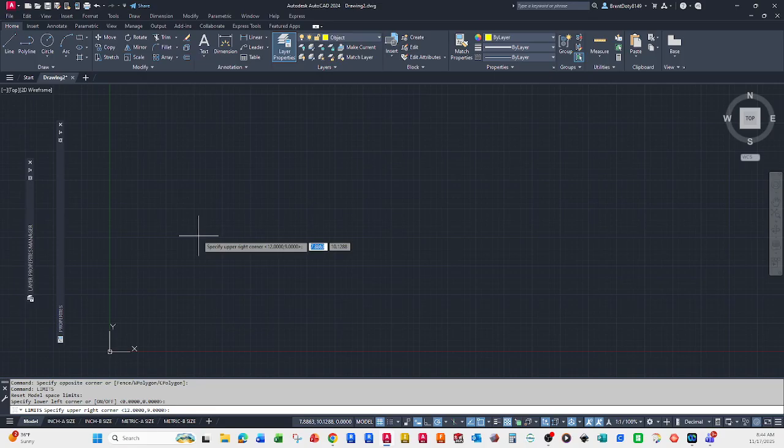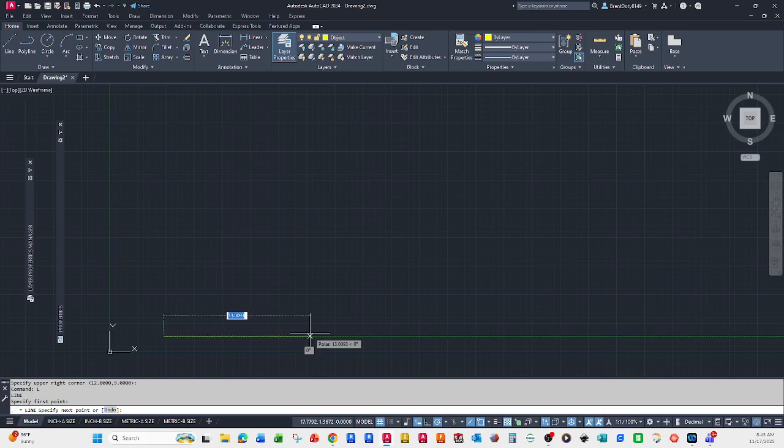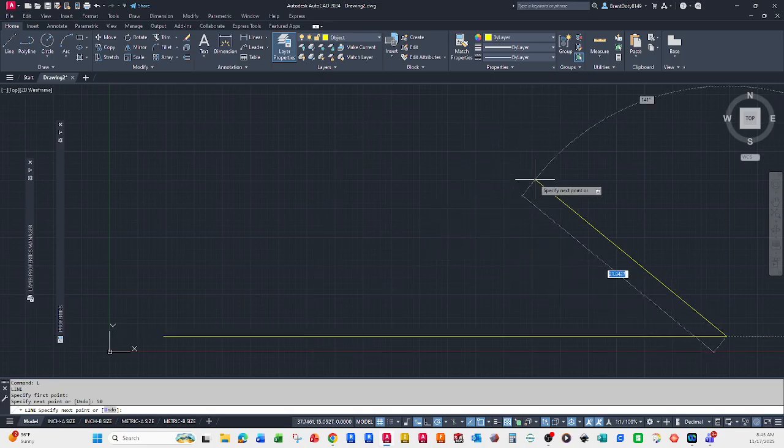You know, it's 70 long, 30 deep, and 50 tall or something like that. Well then, you're going to need more space, because if you try to draw something, it's just going to pop off of your screen, right? Because right now it's set to 12 by 9. Okay, well, if I were to leave that 12 by 9 and draw a line and say, okay, I want it to be 50, then, oh, well, there it is. It's still on the page.